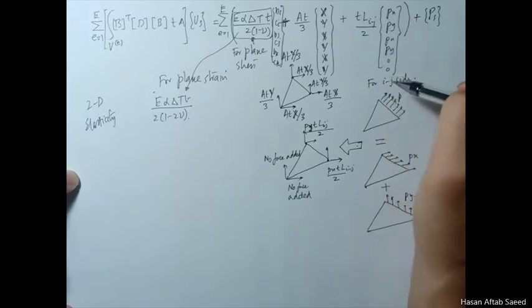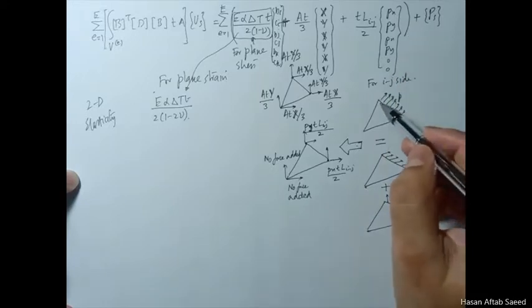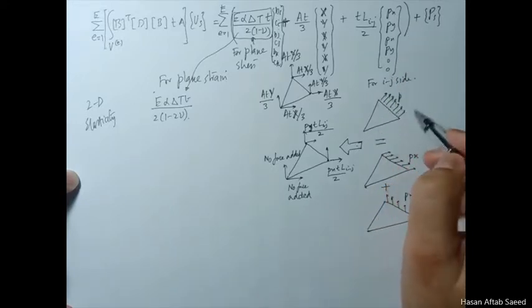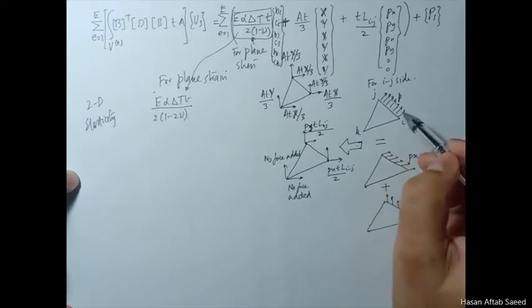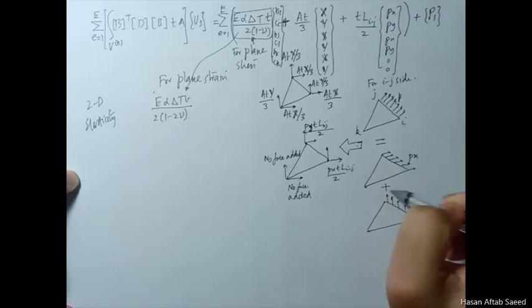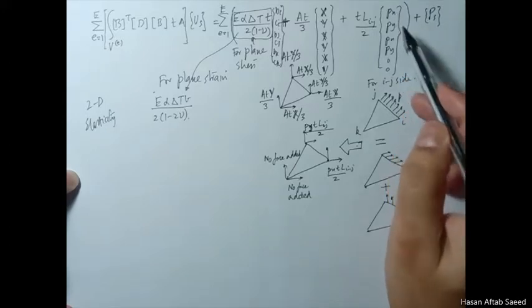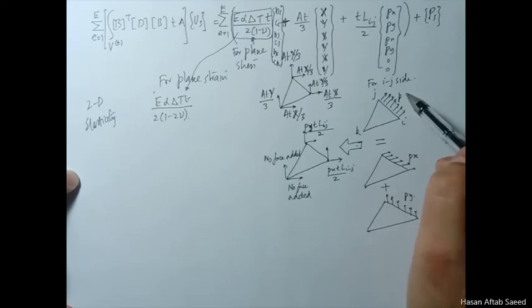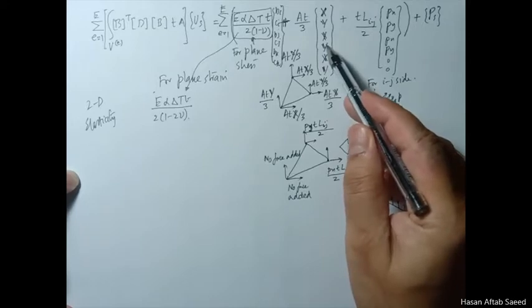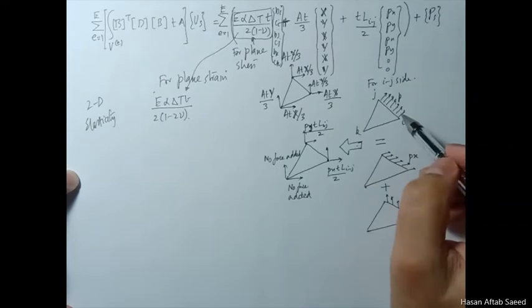This one is the pressure force vector. Now this is the special case of pressure force being applied on nodes i and j, on the ij side. So by superposition, we can divide this into a pressure force in the x direction plus a pressure force in the y direction, and from there you get the components px and py. And again the thinking is the same. You apply this pressure force, which is in Newton per square millimeter. The body forces x and y were in Newton per cubic millimeter, so you had to multiply them with the volume. Here you are simply going to multiply them with the area.